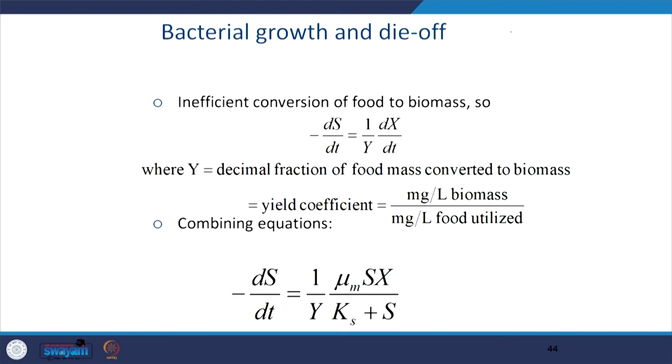So why am I concerned with these bacteria? At the end of the day, I am not here to feel philanthropic and have a lot of bacteria. It is because I want to degrade the waste, which I am representing by S. But what is S going to depend upon? As we know, it depends upon how many bacteria are there. So the rate of removal of S will depend upon the rate of growth of the relevant bacteria.